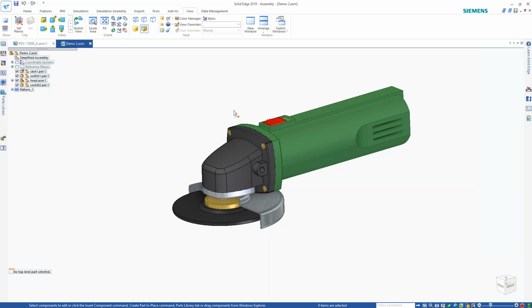Unless you go in and run information on what the density of that part is, and then apply a material with that density to that component. So say you have that in 100 locations, you put that material in with that density for that component. So when you run it with the simplified part in it, because at that point it's not a simplified component, it's the component that you brought in, it would have the correct mass for your top level assembly.